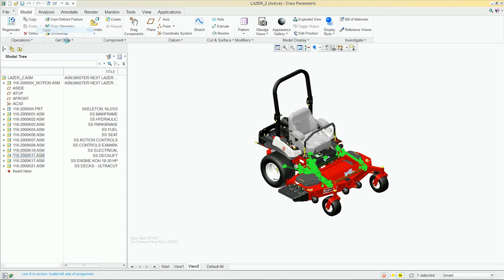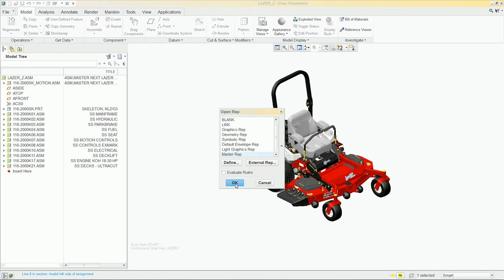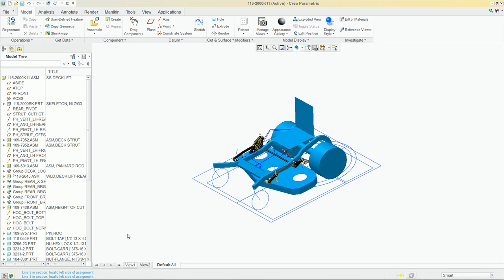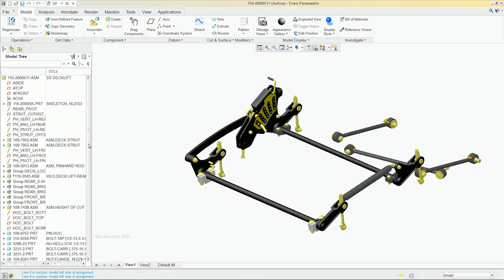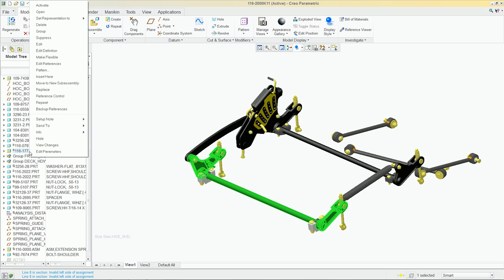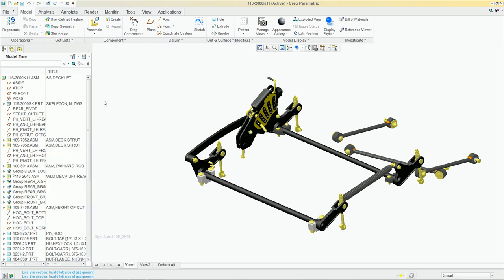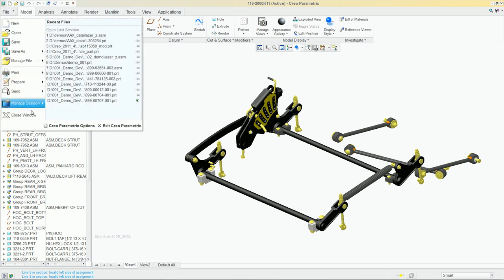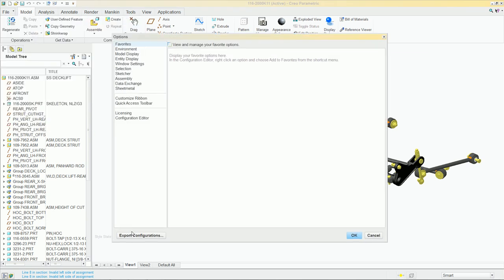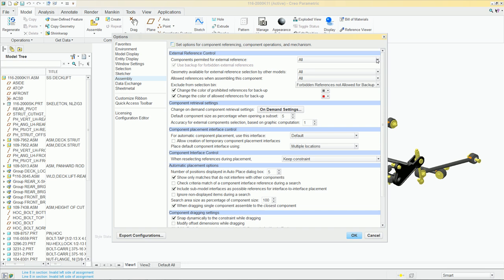Let's take a look at an example. We will need to adjust some simple settings before we use the reference management tool. Some of these settings are to not allow any geometry of an inactive assembly to be changed, and we can also set a specific color to reflect the reference information. We will need to assemble a part into the appropriate subassembly.